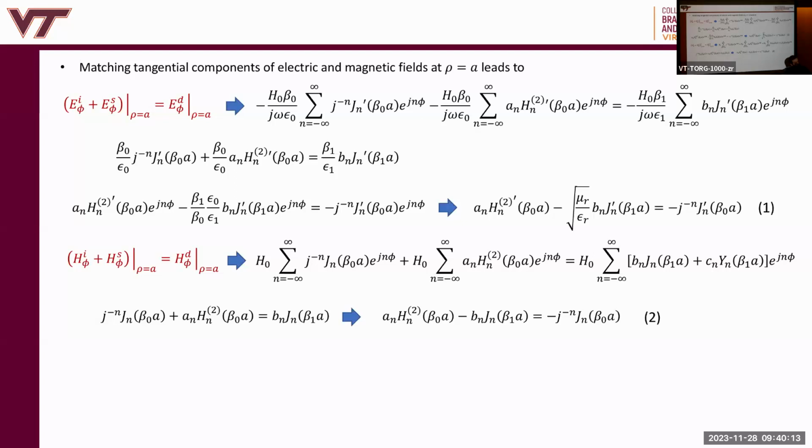So remember, what you need to remember in this class, you need to remember all of it, right? But if you leave here with a solid understanding of the boundary conditions, then that will be a useful thing, right? Because every problem we've been solving ends up being applying boundary conditions, right? Here we are again doing it. So tangential components of E. E phi is the tangential component, E rho is normal, and EZ is also tangential, but we don't have EZ.